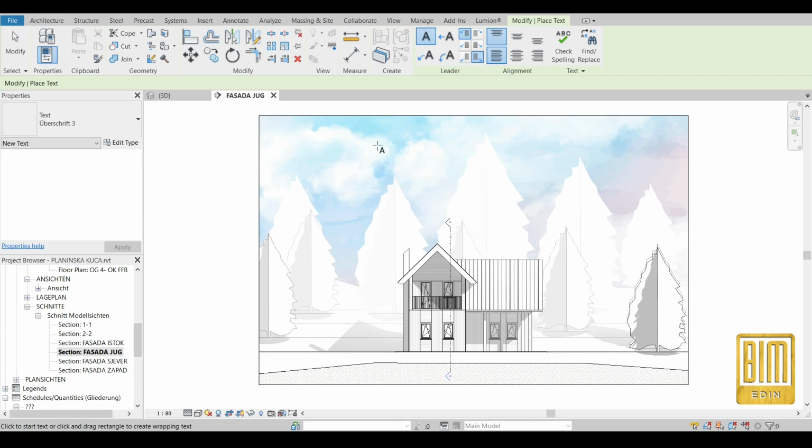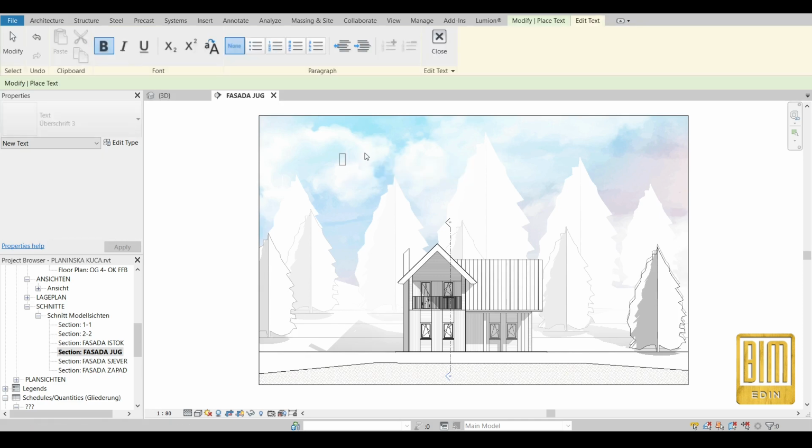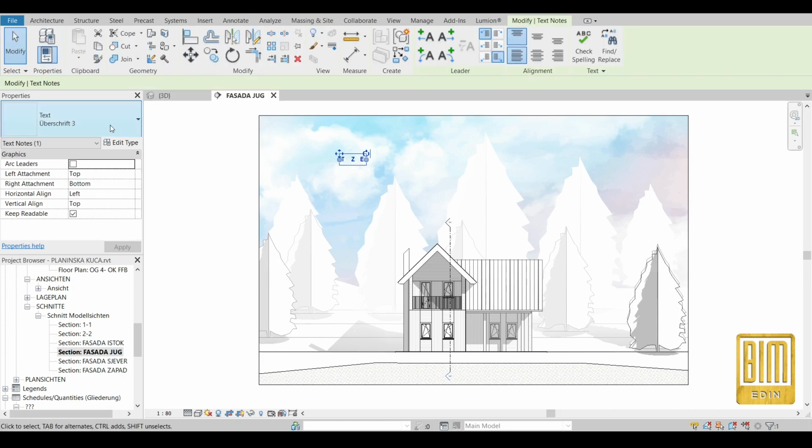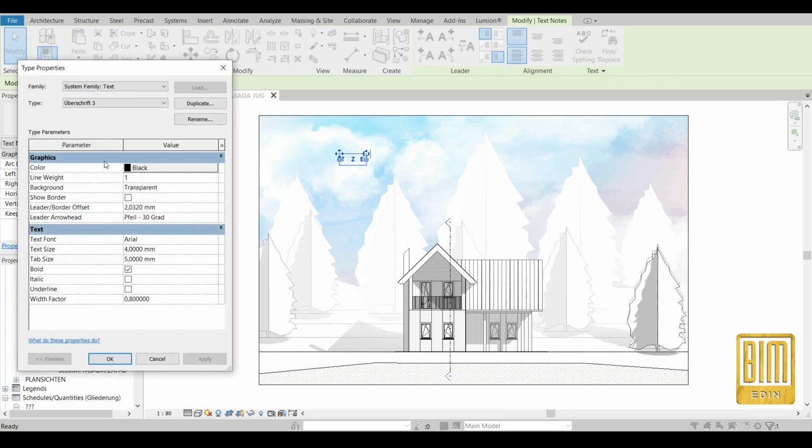Here I will show you how to add birds, silhouettes of birds, using text font. I talked about this in the first tutorial, where I showed you how to create project presentations using consistent visual style, and there you can also see how to add birds using text font.